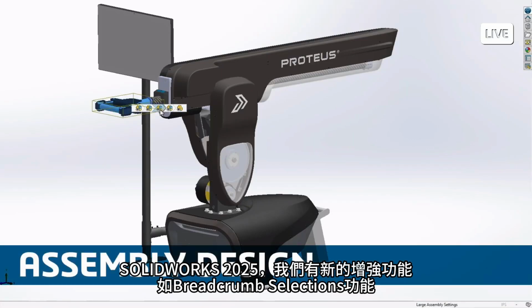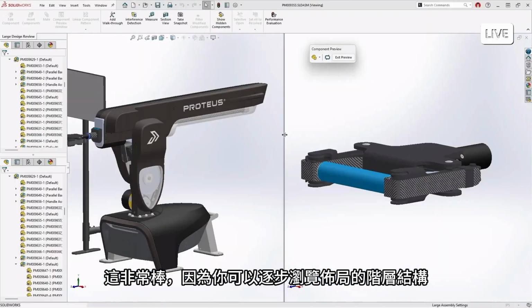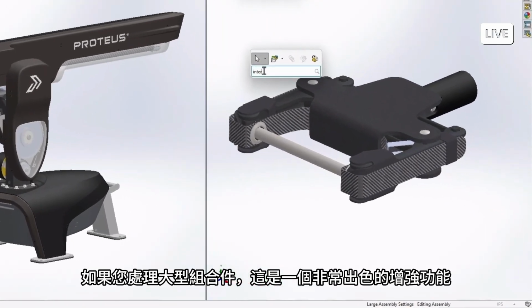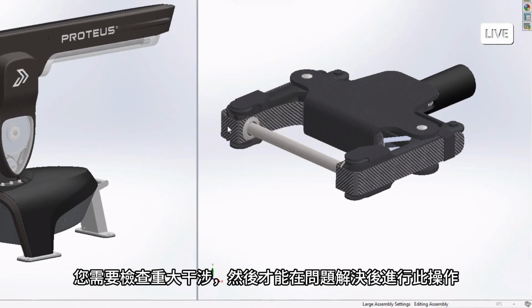Now in 2025, we have new enhancements like breadcrumb selections. This is awesome because you can go through and navigate the hierarchy of that assembly. Now, you'll also see that interference detection in 2025 is now supported for that LDR mode. This is a really awesome enhancement if you're working on big assemblies and you need to check for major interferences. Before, you could only do this when it was resolved.